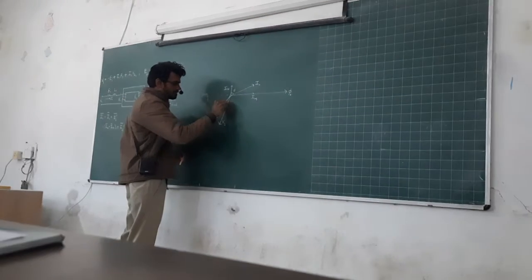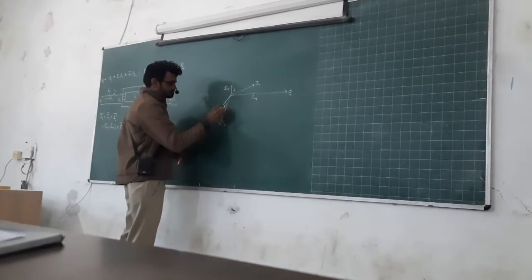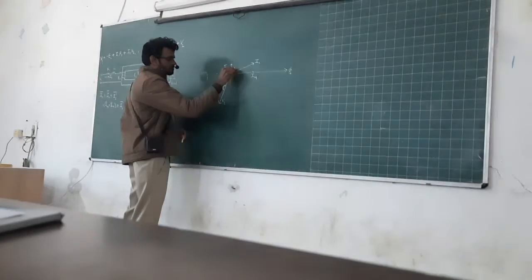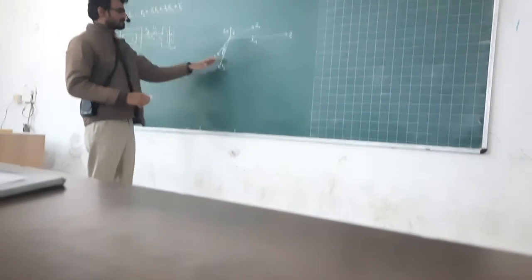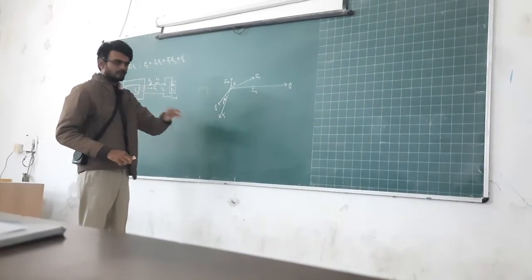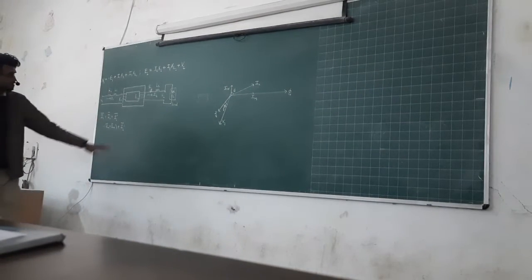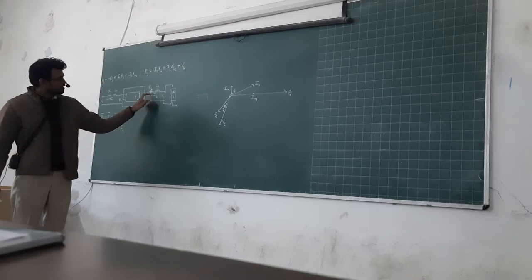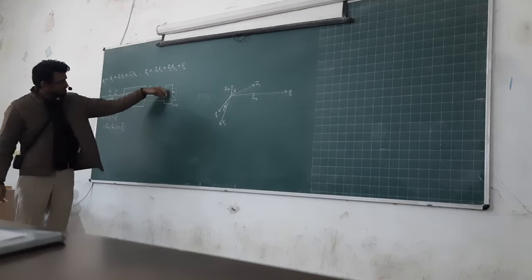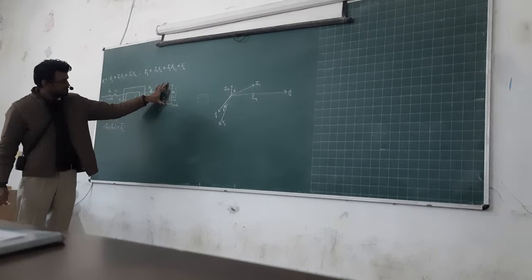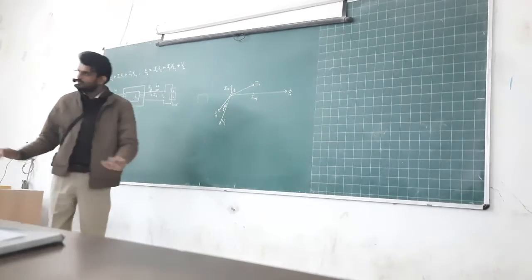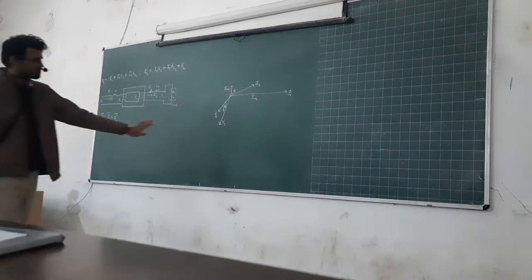And that angle, let's call phi 2. Phi 2 is the angle here. Here the angle is phi 0. Because it is on the secondary side, we give the second number to the angle. So only consider this portion: V2, I2, and the current is flowing in this way. Here the current flowing is I2 and the voltage is V2. So the current lags behind V2 in this portion. Up to now everyone clear? Why does the current lag behind the supply voltage?